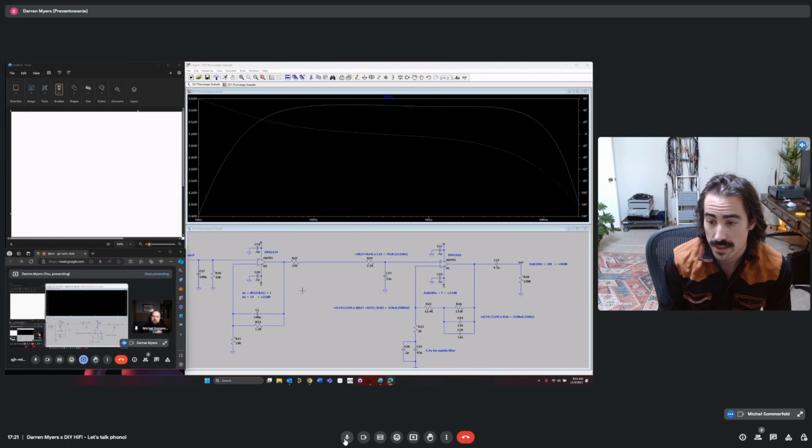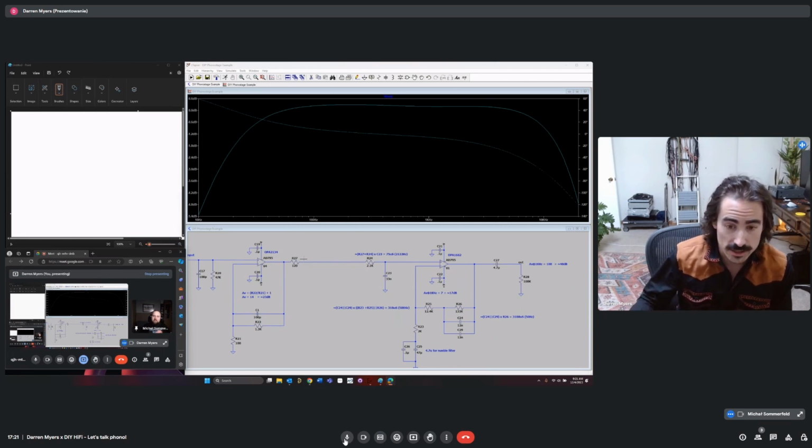I mean, we haven't done anything odd, and we haven't loaded it with any weird capacitive loading. I do have R27, if you notice, separate from R24. We haven't discussed that. That's simply that you need to terminate these op amps very close to their output. This is more of a layout thing where I always put a small resistor right at the terminal of the op amp output.